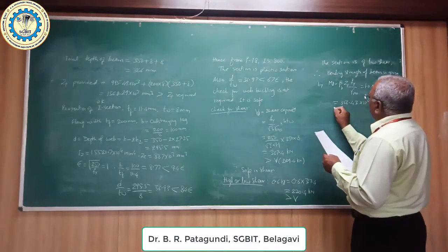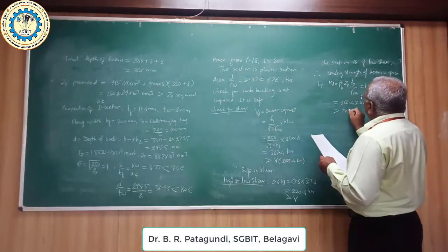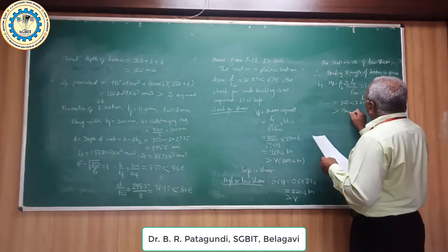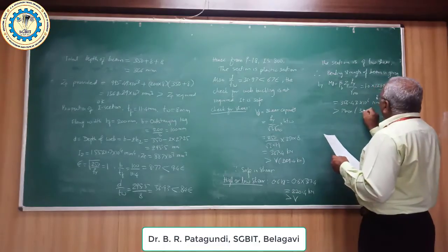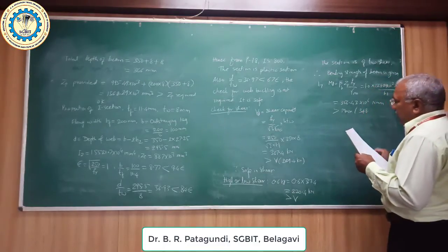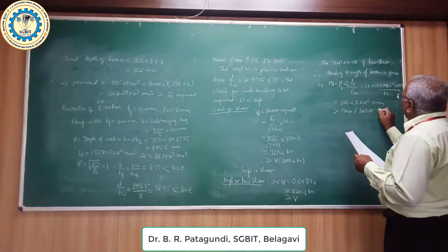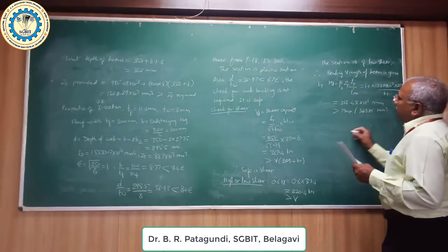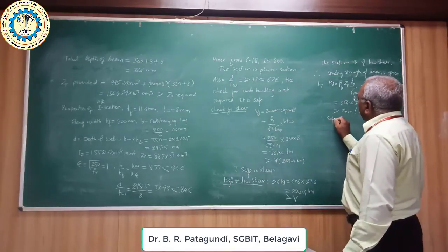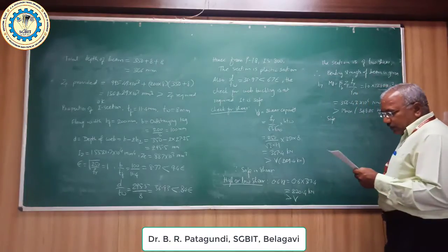It is more than the maximum bending moment, M max, that is 348.25 kilonewton meter. Hence, safe in bending moment also.